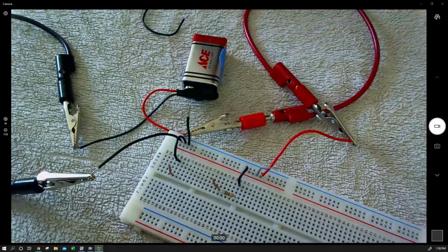In general, as you probably learned from your theory, if we combine two sources in series, their effect will be additive. In DC, they'll just be straight additive. As you'll see in AC, they'll be additive to the extent that they're in phase. And in parallel, the voltage will basically default to the highest voltage, or will be the same if we have the same voltage in both sources, but the current capability of the source will double.